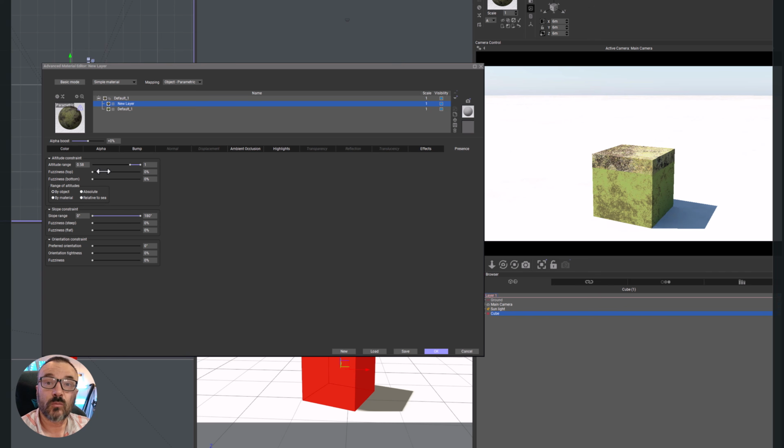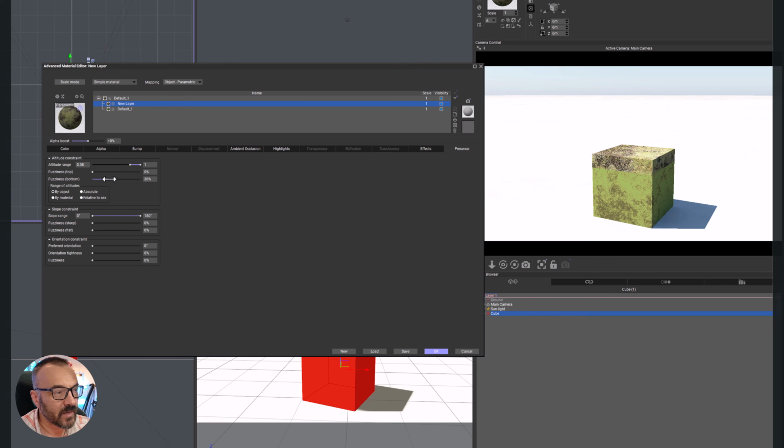And if you use a global material on all of those terrains, they will all be affected the same everywhere. So it's kind of cool. Also, you'll notice it's a hard line. To remove that, you have fuzziness on the top or bottom. If we increase fuzziness, you can see how it's now nice and smooth. We still have it just on top of that layer, but now it's blending a little bit better. Again, I'm saying by the object. Of course, you can do it by the materials as well.